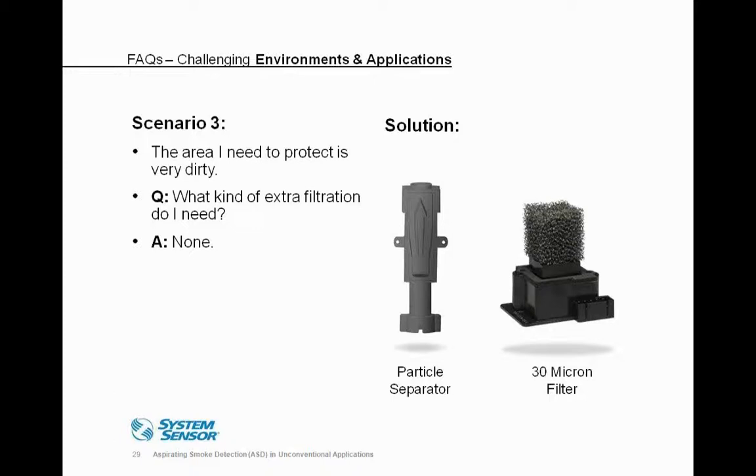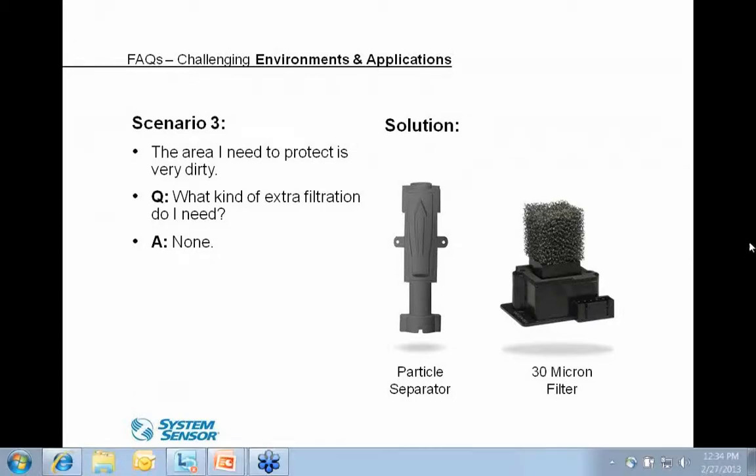The first level is an alert, and you have 72 hours to correct that. If it's not corrected, it turns into an urgent trouble, letting you know that the filter definitely needs to be replaced. It's simply removing two screws on that filter cartridge, inserting the new filter cartridge, and tightening down the screws. There is no certification needed by whoever is doing the filter replacement. It's just a matter of inserting the new filter in place, and the product will tell you when the filter needs to be replaced.